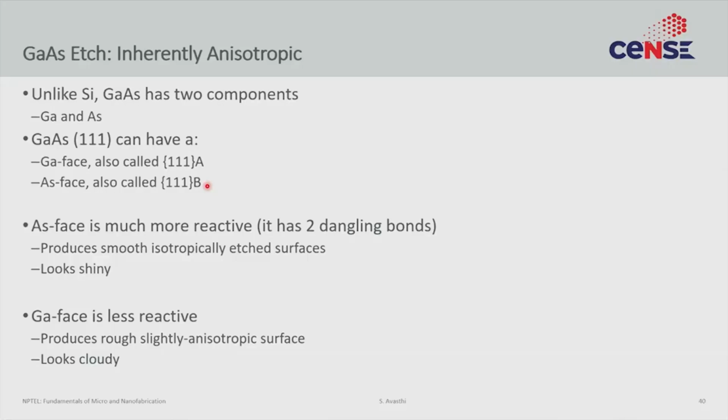Now imagine you're having a tertiary material. This becomes even more complex. To cut a long story short, it becomes increasingly harder for these complex materials to find etches that are truly isotropic, that actually etch in all directions equally. That is because there is no isotropic property that you can actually use to design an etch that is isotropic. So the canonical gallium arsenide etch is also an anisotropic etch. There is really no isotropic gallium arsenide etch per se. Okay, so that's point number one to remember.